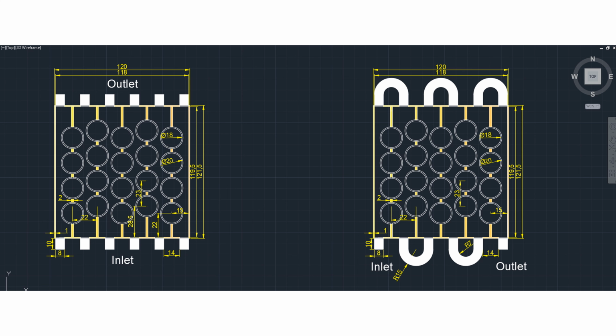We'll start the object with one thing: either you can specify only the fluid zone and you can specify the casing also, or if you want you can actually avoid the casing part also to reduce the complexity, in order to reduce the number of nodes and elements in a given case. So likewise there are two approaches, as I said earlier. You can directly proceed by considering the fluid zone and the cells.